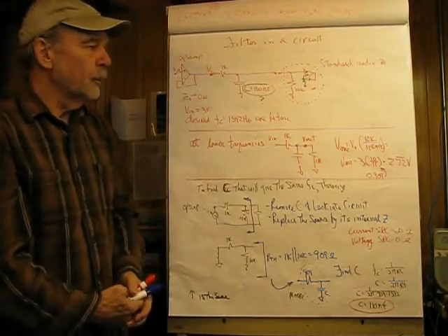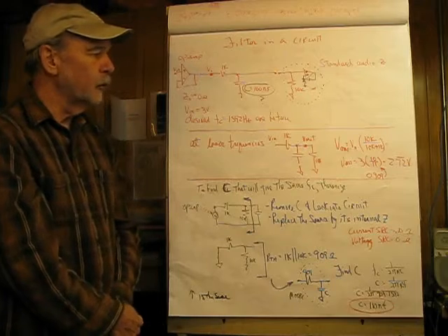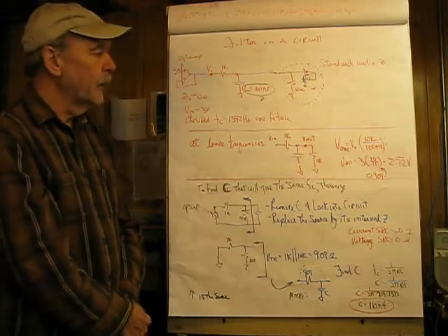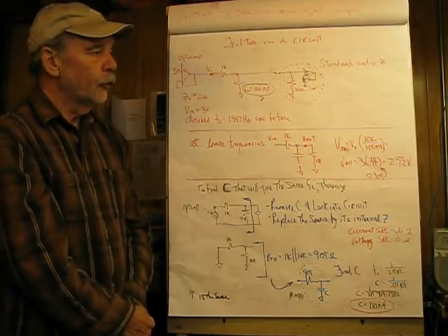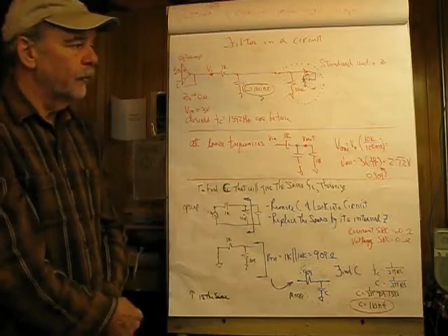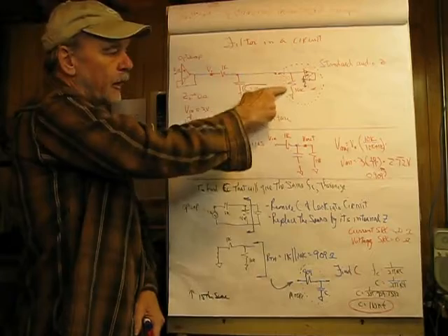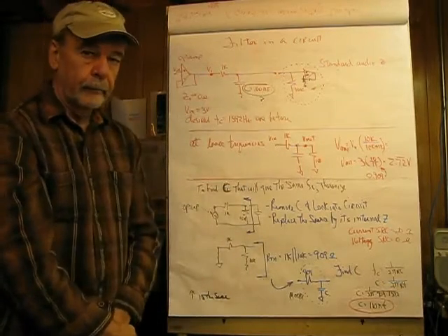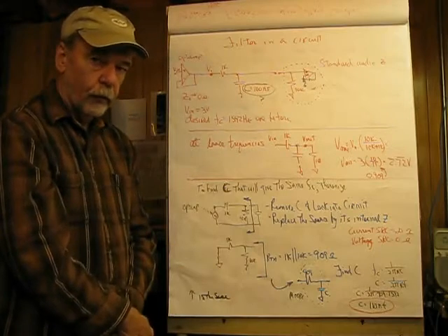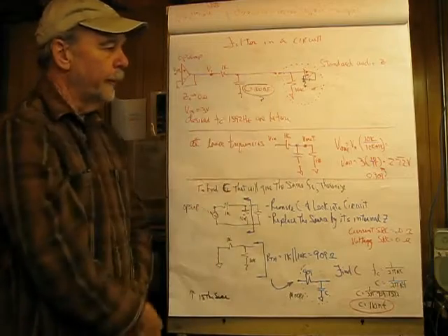So let's do something useful here. And we're going to take our little filter circuit and we're going to connect it into a real circuit. And the concern here is the driving impedance and the load impedance. And what I've done here is connected this into a non-inverting op-amp, and I'm providing a bias path to ground of 10K, and a lot of audio processing consoles and so forth use 10K as a standard impedance. And I've got a little open there kind of to show that.